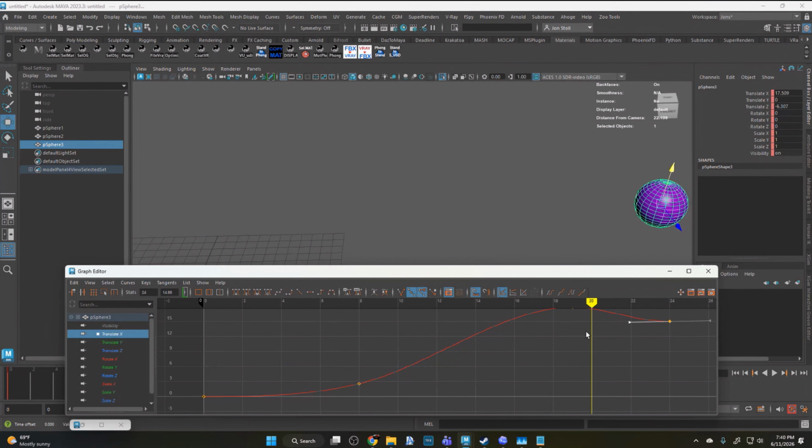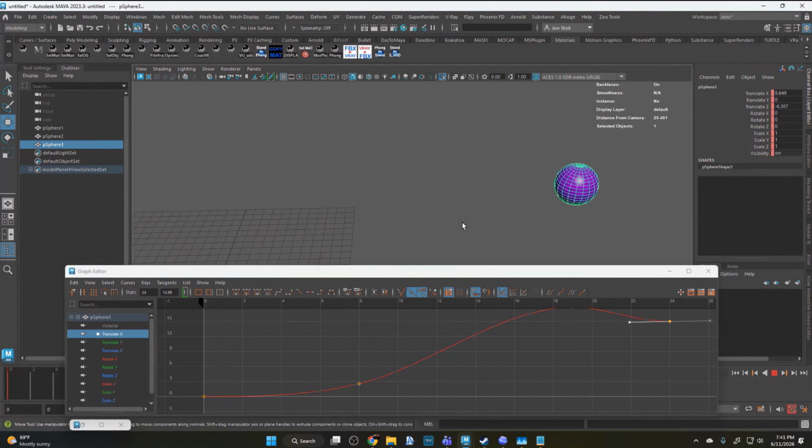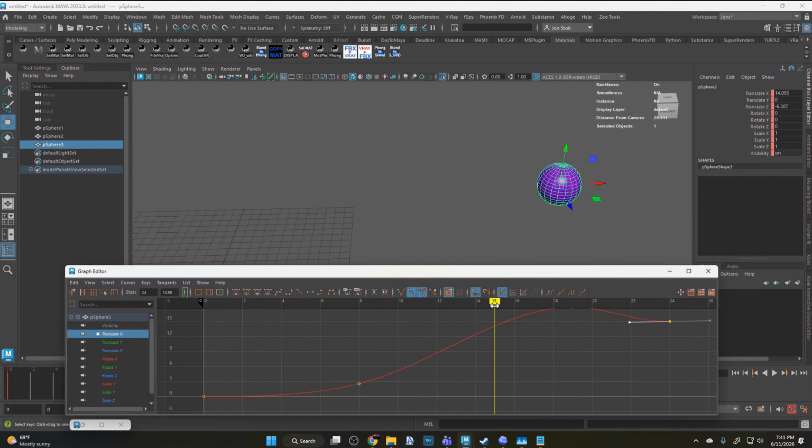To its place, so you've got that overshooting and then bouncing back. You could drag that handle back down and create a little back motion as well. It is going past our point and coming back here. What I mean is it's going past the point and then on the way back, you could pull that handle down and have it rebound just a little bit more and then finally settle on that last point. Not that point, but the left Bezier handle. Drag that one down. No, down. There you go. That's a little bit much maybe, but that would look like an elastic landing. You know, it's going past it, bouncing and then landing there.